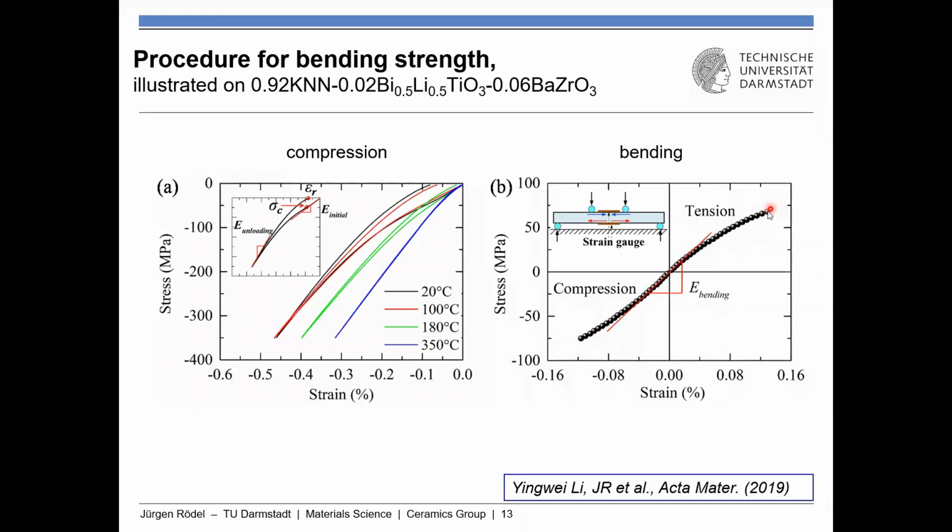So what you do when you measure a bending strength and you put in the usual equation, you really only say, okay, it has a certain strain here. And from there, you really go up and say this is the strain. Then you think it's linear elastic. You think this is the stress, but in reality, this, of course, is the stress. So that's the mistake you make.